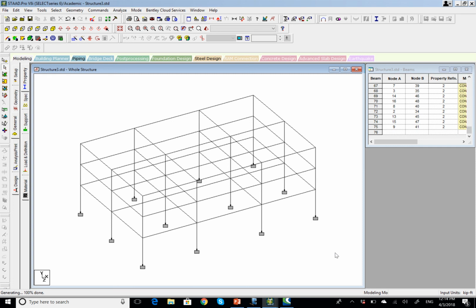And the plus and minus signs, so 2 times 2, you have 4 load cases. Okay? It's not 4, it's 8. Why 8? Because this is a flat roof, so to calculate the wind load on the flat roof, you have to use the ASCE 7, chapter 27. And you're going to see that CP has 2 different values. So you're going to have 2 different load cases multiplied by those 4 load cases. So you have 8 different wind load cases.